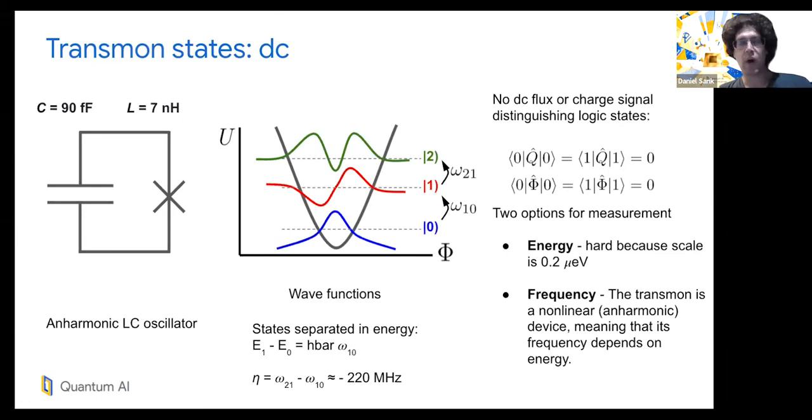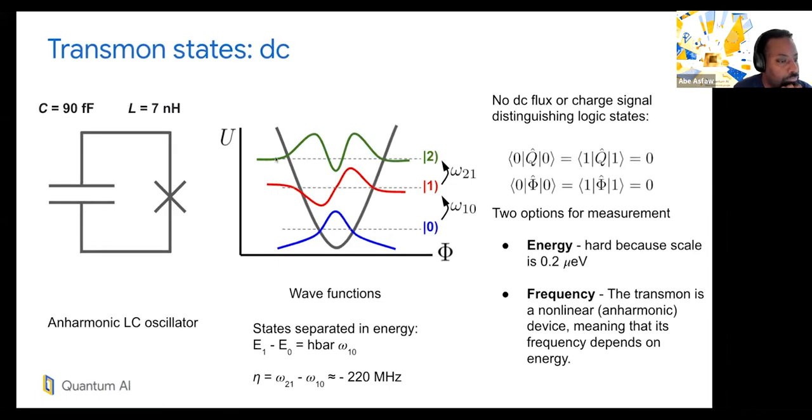First I want to explain why it's difficult to read out a transmon qubit. The circuit diagram you see on the left has a capacitor and a Josephson junction in parallel. That's a transmon qubit. Now, as a quantum mechanical object, this thing has a cosine-shaped potential energy, as Abe showed you earlier. And if you focus on one of the wells in that cosine, it looks kind of like a parabola, but it's got some funny curvature to it, as Abe explained.